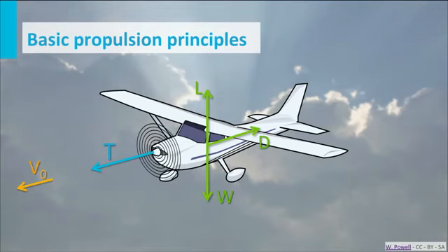It's important to realize that the airspeed of the aircraft, from the engine perspective, if the engine is your frame of reference, is also the speed with which the air enters the engine or the propeller. And therefore this is often indicated with the symbol V0. So that's the speed with which the air enters the engine or the propeller. And this V0 is used as a starting value. But that only refers to the standard airspeed of the aircraft, the true airspeed of the aircraft.